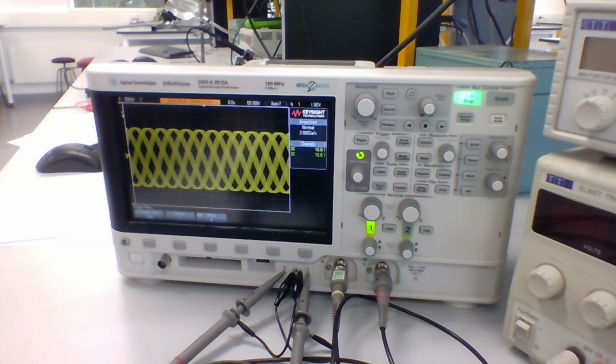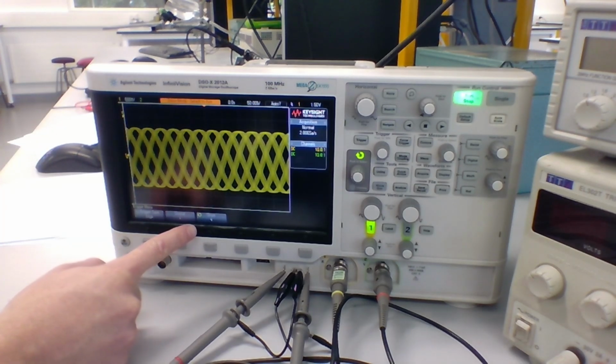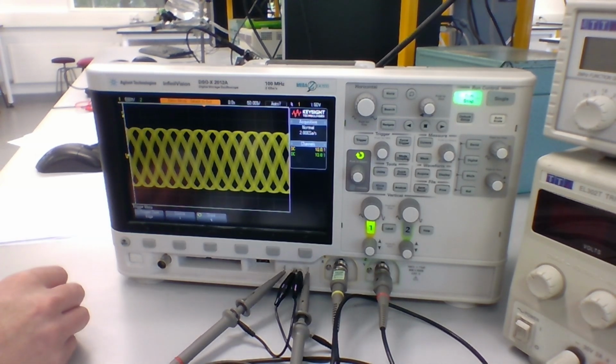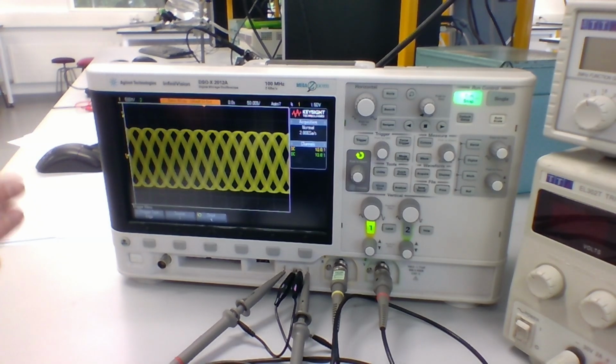If it can't find something, so in this case, if it can't find a falling edge of this sine wave that is crossing 1.5 volts, so the sine wave decreasing from above 1.5 volts down to below that, it'll basically take a bit of a guess. It'll say, well, I haven't measured anything for a while, I'm just going to take a measurement now. And it does that. It tries to make a good guess when to do that, but it's more or less just taking a guess.